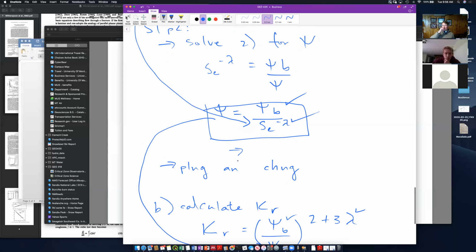Well, usually if you're not getting the right curve, then that means you got an error in your equation. But here there is a statement, and that is that if psi is greater than or equal to psi sub B, psi is equal to psi sub B. And that's just for the Brooks-Corey equation.